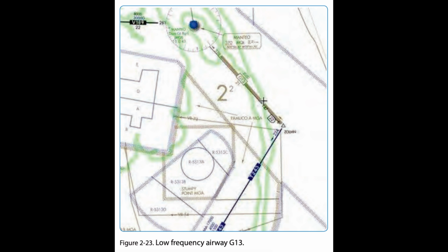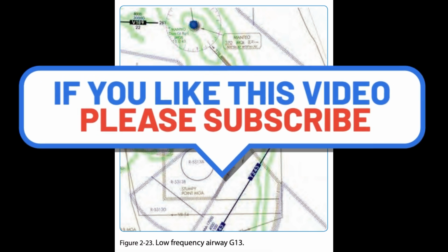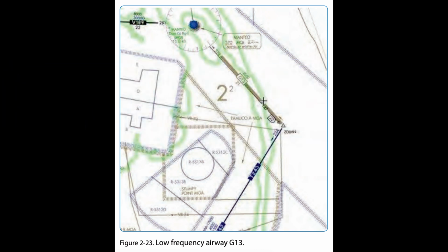They are the Federal Airway, consisting of VOR Low Victor Airways, High Jet Routes, NDB, Low or Medium Frequency, and the RNAV route system. To the extent possible, these route systems are aligned in an overlying manner to facilitate transition between each. The majority of the airways are made up of Victor Airways, Jet Routes, and RNAV, but some low/medium frequency L/MF airways and routes are still being used in Alaska, and one other that is located off the coast of North Carolina and is called Green 13, G13. Figure 2.23. Airway/route depiction.